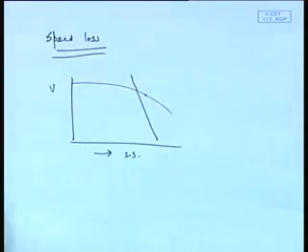Obviously you don't want to do that, but this is what is known as voluntary speed reduction. That means you deliberately reduce the speed, otherwise you have very excessive motion. So this is also another part of seakeeping which is important when you are going on a rough sea.